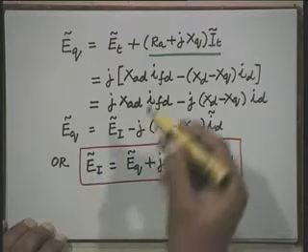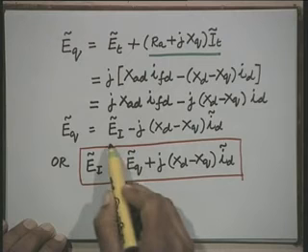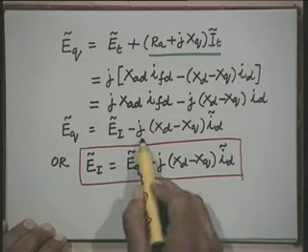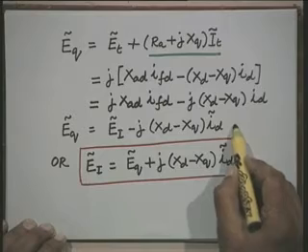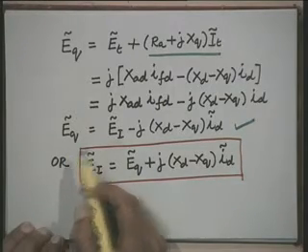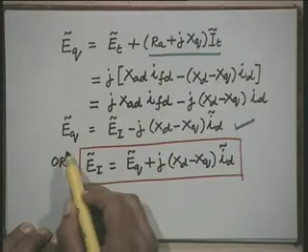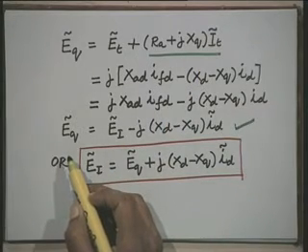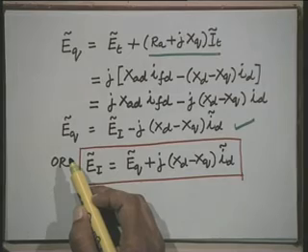Therefore, this E Q in the phasor form is represented as E I minus j times x d minus x q into I d. That is, we can express this E Q which was defined earlier as a voltage behind this impedance. This is also along the q axis, and we have seen actually that it is this voltage phasor which defined the location of q axis with respect to the terminal voltage.